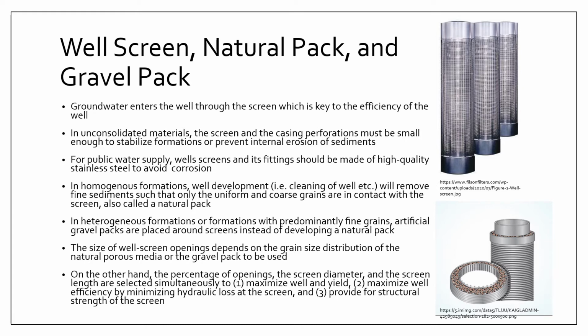Take good note that the screen is basically the entrance of the water to your water well, and any mistakes in the design of your screen can severely impact the efficiency of your well, meaning you can get smaller water well yield, or you might end up with a well that needs a lot of pumping, hence electricity to operate.